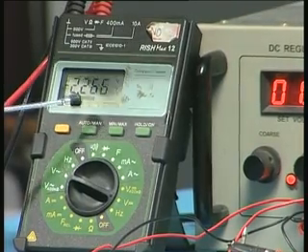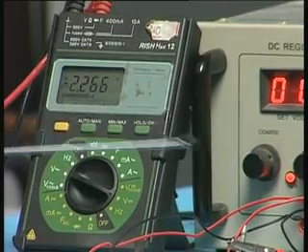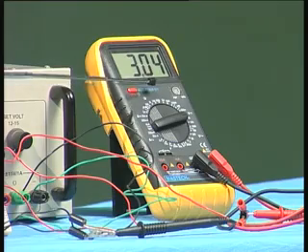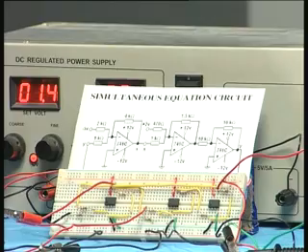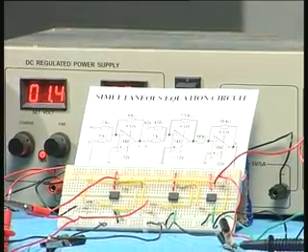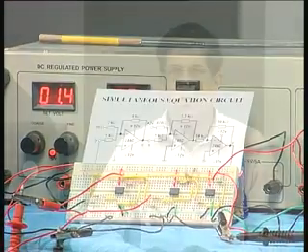That gives the solution with reference to X, and this multimeter gives the value of Y, and this is what we have actually done as an application of the operational amplifier mathematical operations. So I have actually shown you a real circuit which is implemented using these two equations, and we found that the values of X and Y correspond to the voltages appearing when I measure the X voltage and the Y voltage. That will correspondingly give me the solution of the equation.